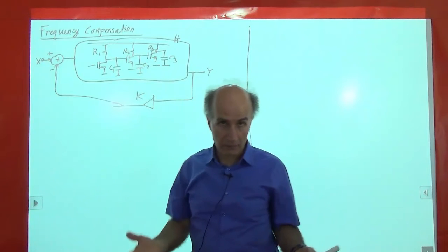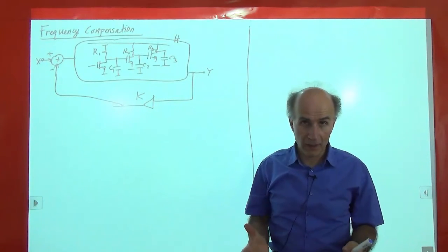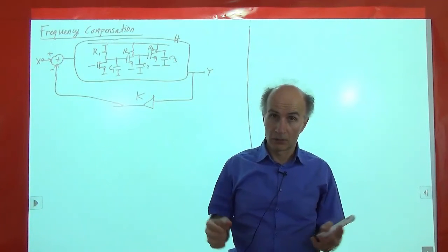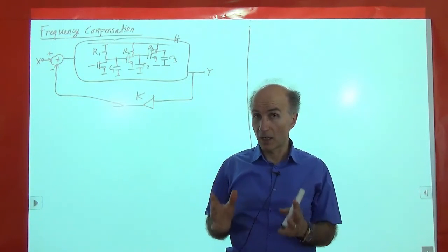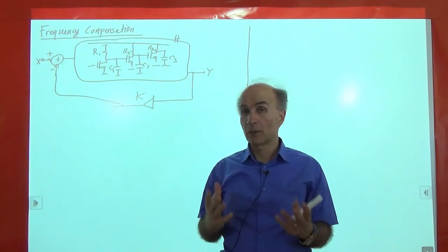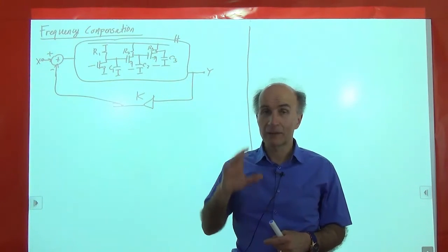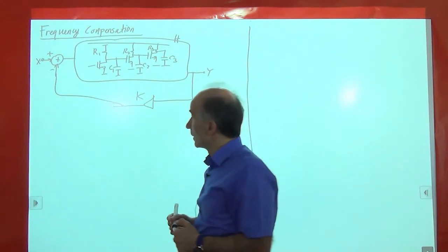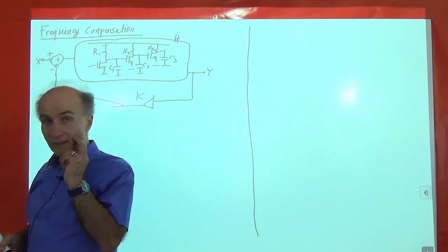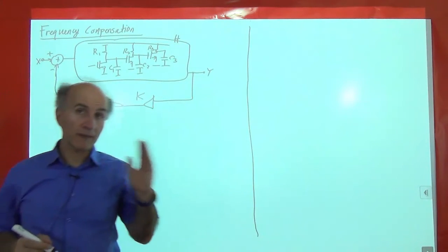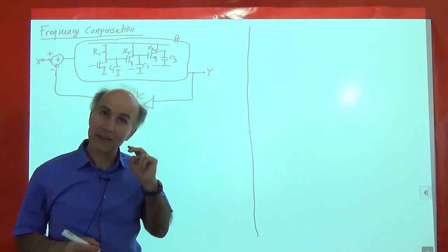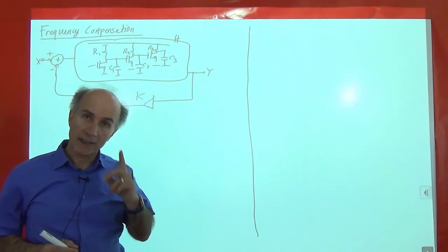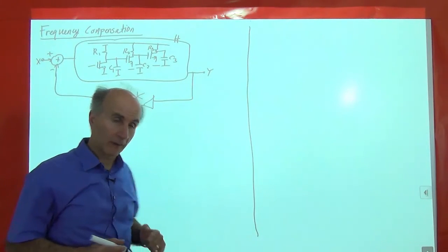We plotted the magnitude of KH, the phase of KH, and we saw that the phase margin was 0 or even negative, meaning the system was unstable. So now we need to stabilize the system, and that is called frequency compensation. Okay, so I showed you two examples before, where we saw that the system became more stable. And in fact, those are exactly what we call frequency compensation. We will focus on the second one because that's the more important one.